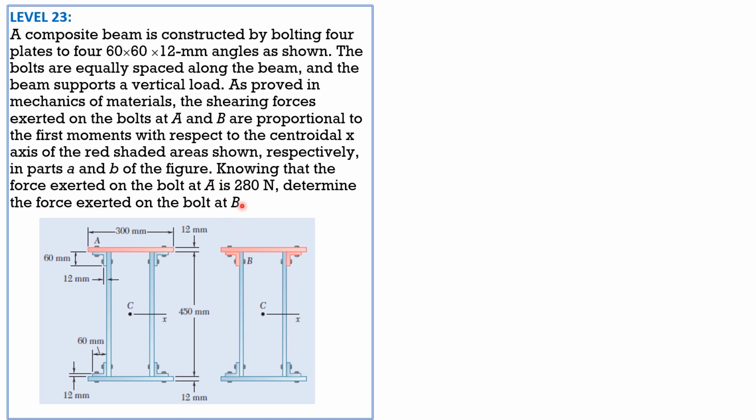As stated in this problem, the shearing force is proportional to the first moment of areas of these shaded red areas with respect to the centroidal x-axis, which is obviously by symmetry here through C, a horizontal line through C.